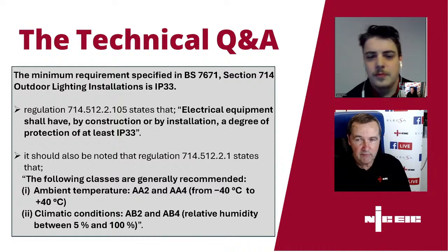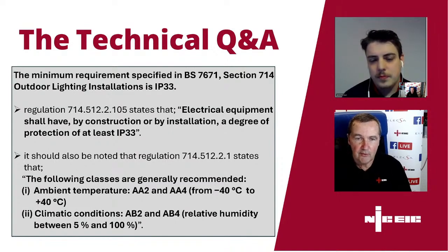So what you've got to think about is: for the time it takes the protective device to operate, can I make sure that simultaneously accessible parts are not going to rise to a different potential, which is going to involve electric shock? Normally we're talking about all of the metalwork, the trunking, the distribution boards, etc. in the intake room, and we bond that all together so that we're not going to see any potential differences.